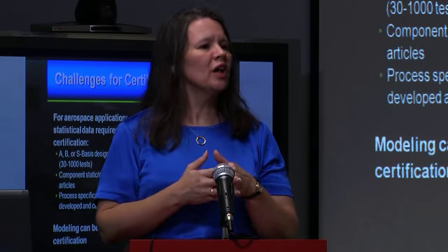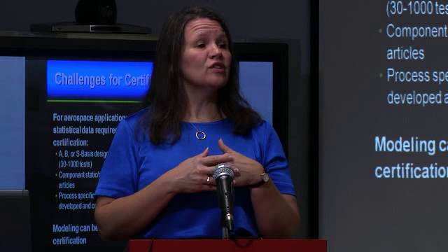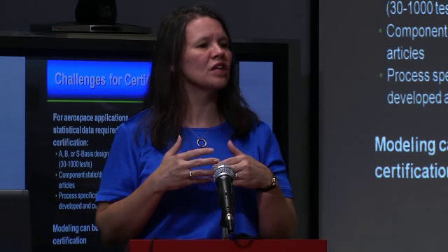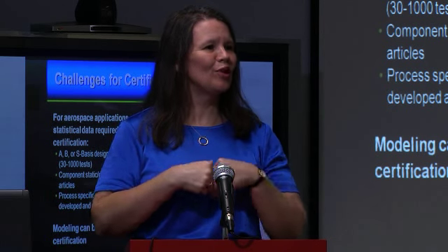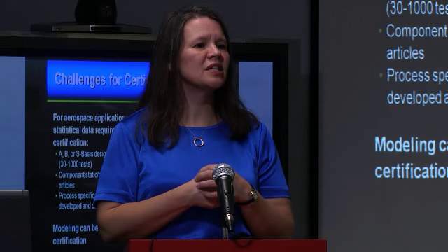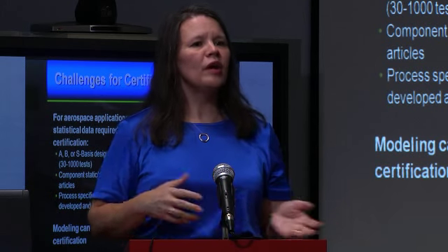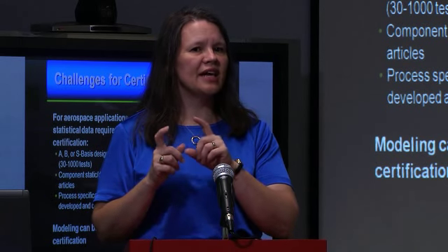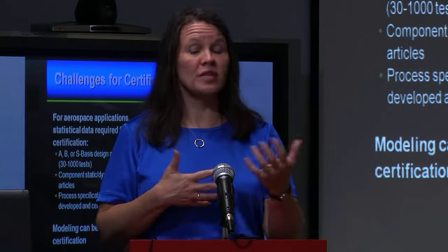To put something onto a flying airplane, you have to have A basis allowables, which is upwards of more than 1,000 tests. And so it requires a lot more rigor. There's a lot of requirements on how many different places have to build the parts and how many different heats you have to use in order to get the statistics. That basically means if I do 1,000 tests and I build this database, then if I build a part to put onto this airplane and do a test from that part, I can say that yes, that should fall within the statistical database from this S basis allowable or from this A basis allowable.